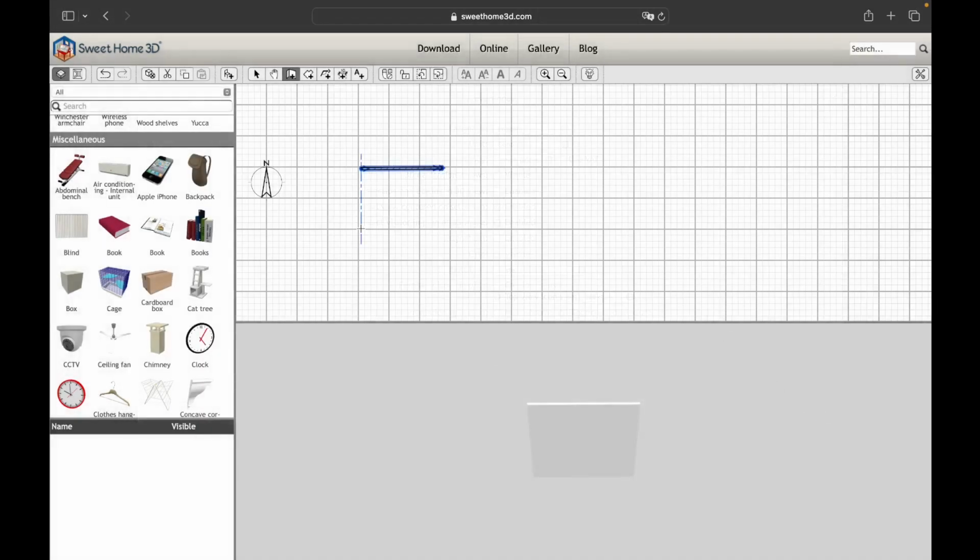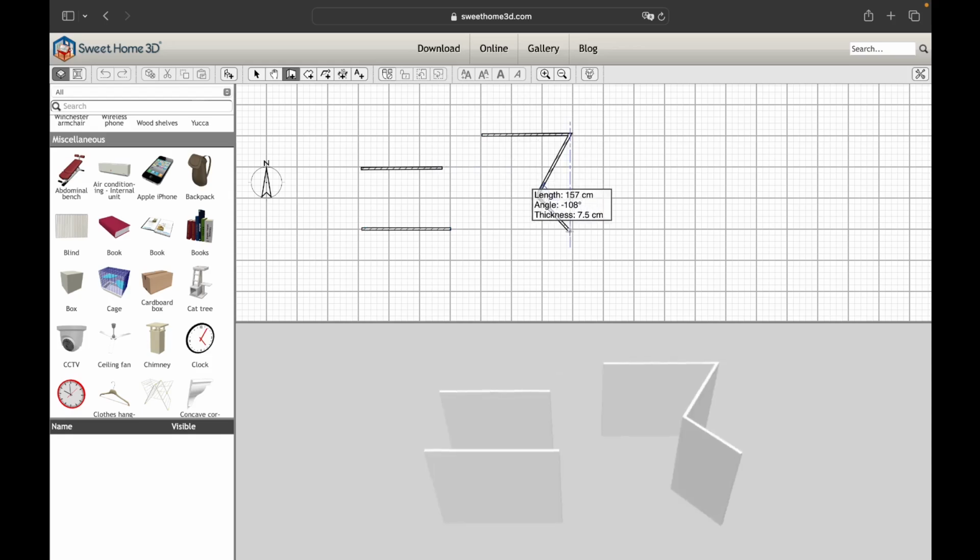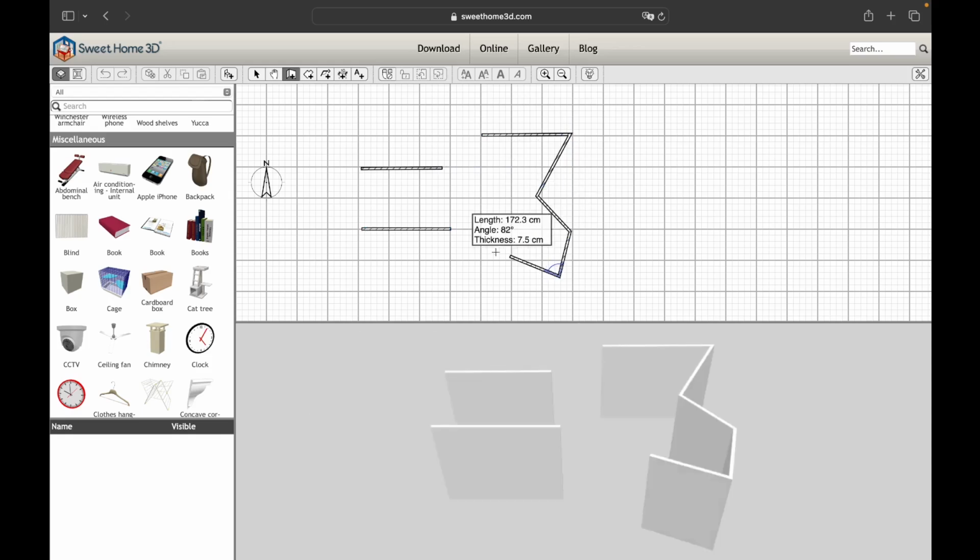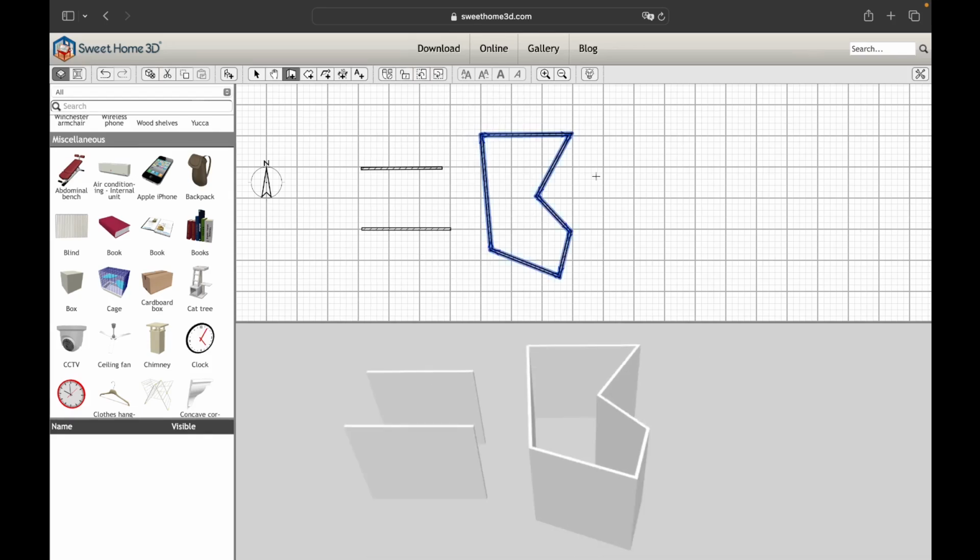To determine the final point of the wall, we do a double click with the left mouse button. In another case, by making a simple click, we establish the end of the wall created, but also the beginning of another. In this way, it is possible to create a closed or open environment continuously. To finish a wall and start another wall, we press the left mouse button once, and when closing, we press twice.